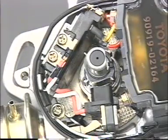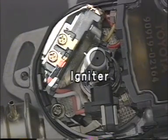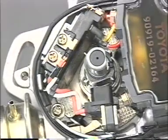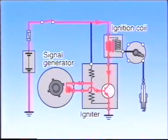These changes in the EMF cause the igniter to switch the primary current on and off. Let's take a look at how the current is turned on and off. When the engine is running and one of the signal rotor's teeth approaches the pickup coil, the voltage is generated in the direction shown in the diagram. The base current flows in the transistor, switches it on, and the primary current flows in the coil.